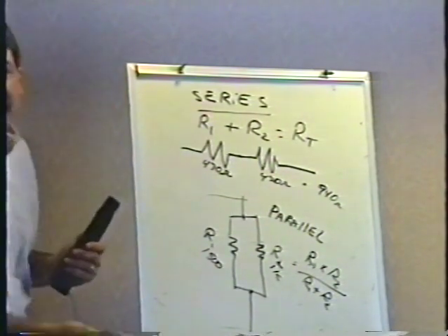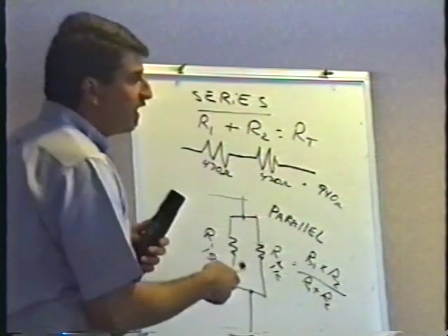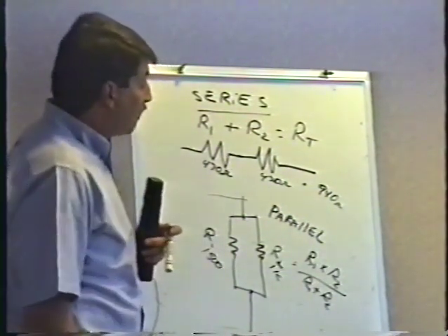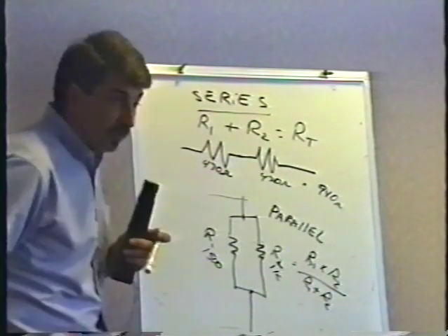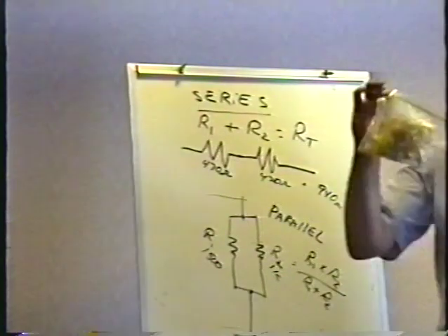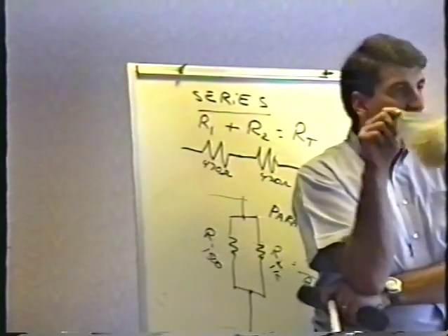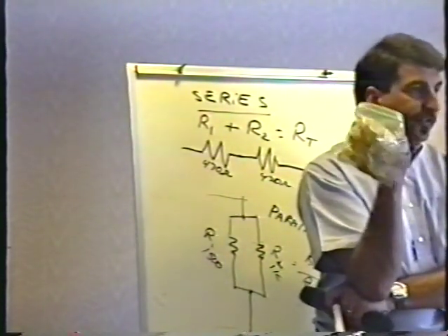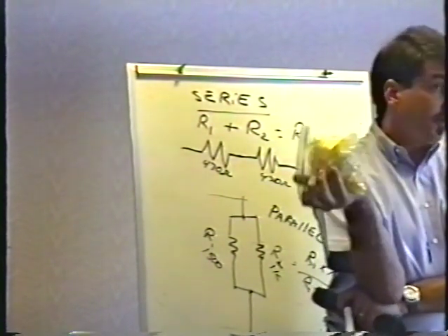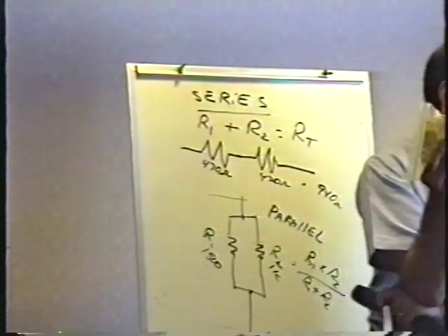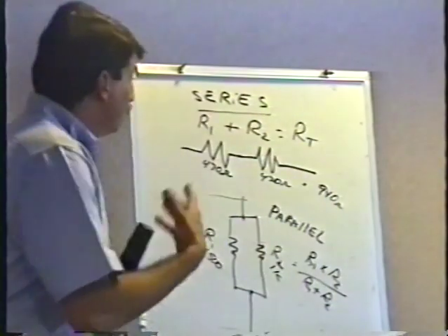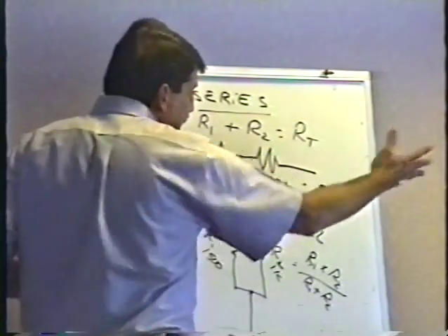You could do this. I've done this more than once. And I'll show you later on with something called a capacitor, where you really sometimes need to do this too. But quite honestly, since resistor failures are so rare, and a bag of resistors like this costs you a couple of dollars for a giant bag, even from Radio Shack, there's no reason why you shouldn't be able to come up with the correct value resistor, to be honest with you. But as far as simple work like that is concerned, putting them in series adds them up.